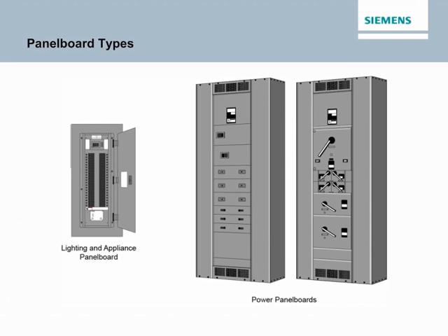For example, a lighting and appliance branch circuit panel board had to have more than 10% of its overcurrent protection devices, that's not including the mains, protecting lighting and appliance branch circuits. A lighting and appliance branch circuit is one with a connection to the panel board neutral and an overcurrent protection device rated for 30 amps or less. For the purpose of this definition, each pole of a device is considered as one device.